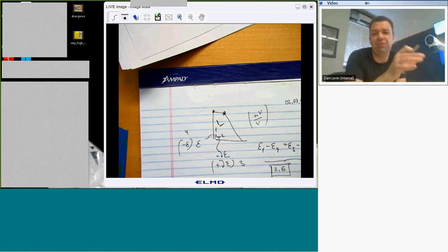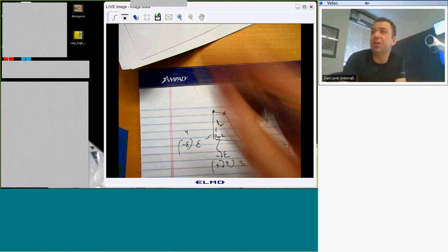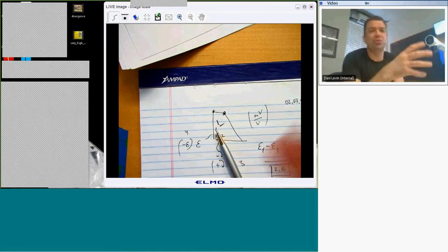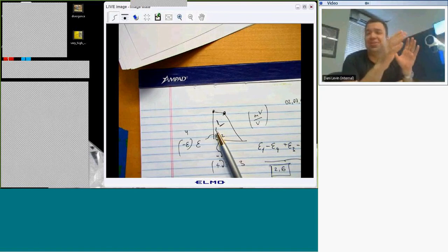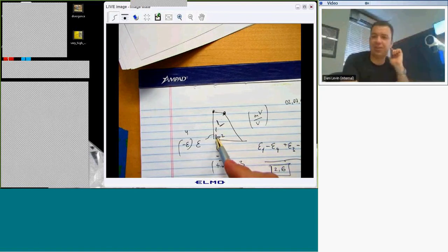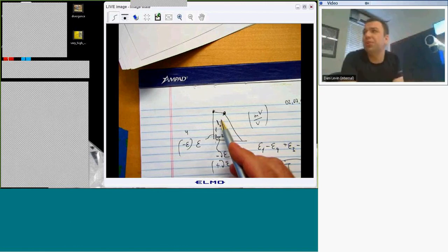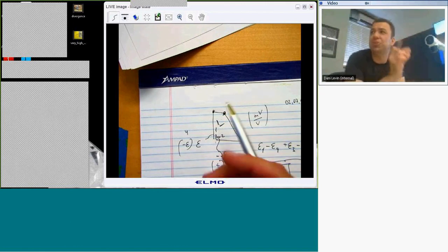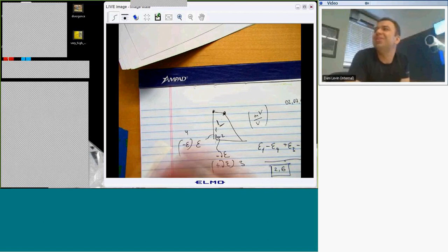We will have our frequency reading of these two bridges. So potentially the ideal thing is that you will have the bending reading around 4 Hertz, and the torsion reading you will have around 15, and you will have them shifted. If we will be measuring 1 and 2 separately, then we can say if it is going to pure bending, some value of epsilon we are getting from those two, we can say that it is going to on bending mode or something like that.